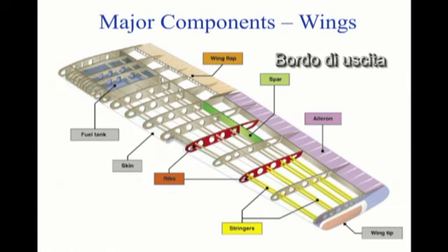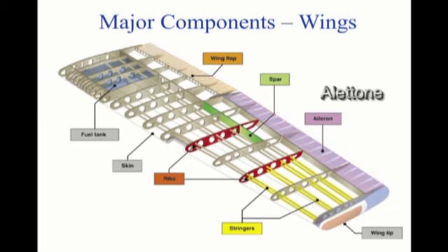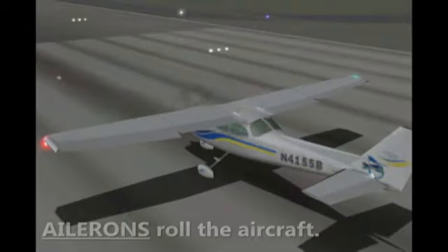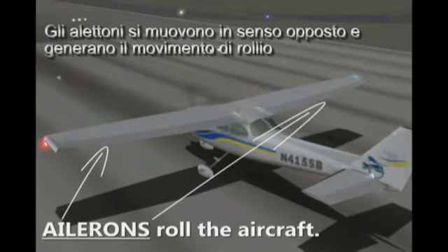Attached to the opposite side of the wing, or trailing edge, are two control surfaces called the aileron and the flap. Wings are exact mirrors of each other and contain the same control surfaces on both sides of the airplane. Ailerons extend from about the midpoint of each wing outward toward the tip and move in opposite directions to create aerodynamic forces that cause the airplane to roll.